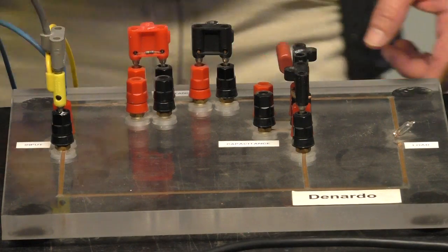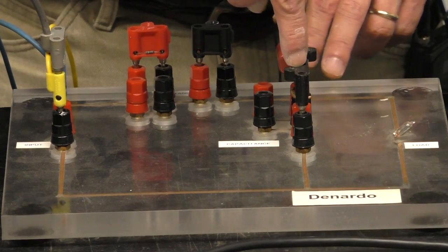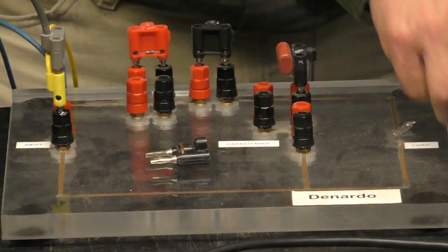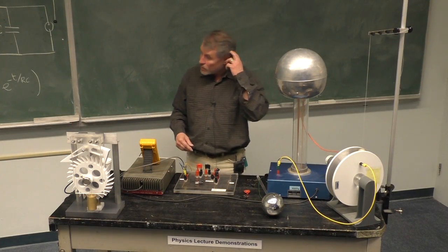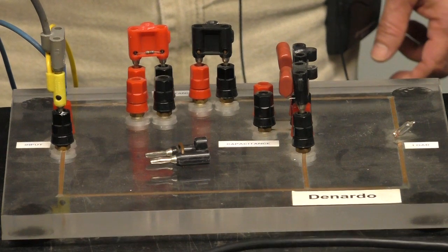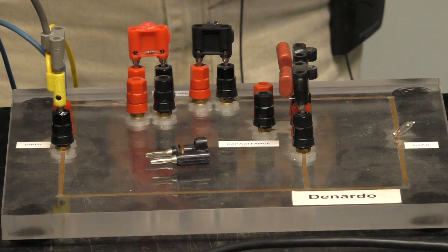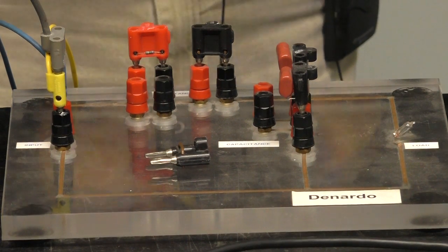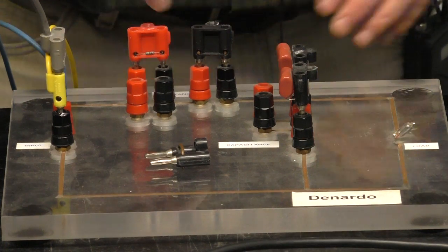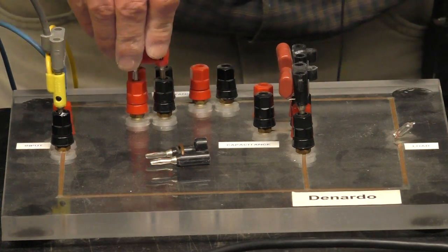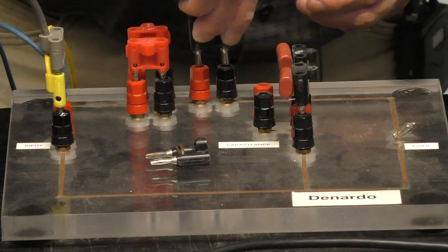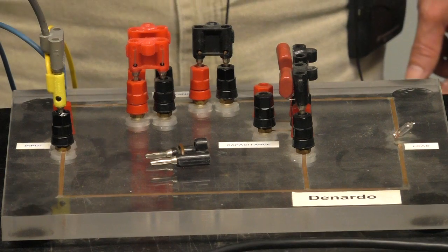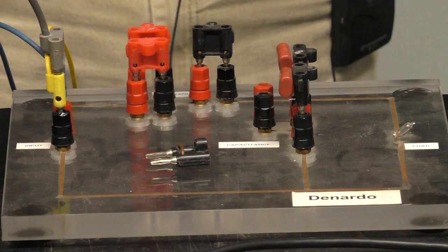Okay, so I can reduce C by putting another capacitor in series, right? So let me take this off. I'm going to put another capacitor, reduce C, and so RC comes down, so the time between flashes is reduced. Similarly, I can reduce the resistance by putting a resistor in parallel. Half the resistance and half the capacitance is a quarter of the timing, okay?